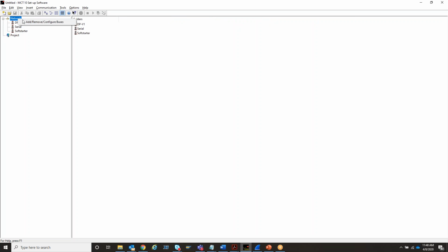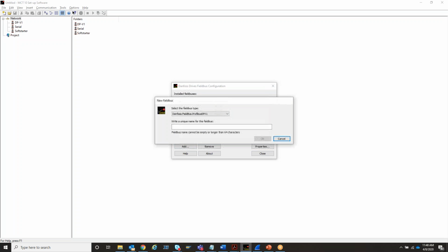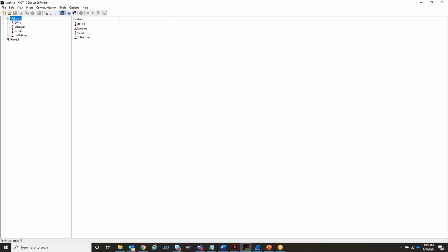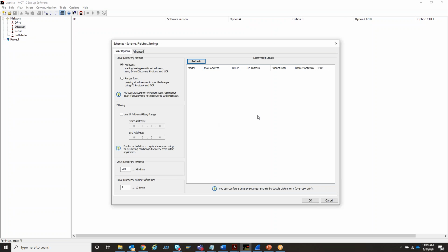So yeah, there's 2 different ways. I can connect through USB, or there's Profibus connection, but there's also the Ethernet. So I can actually connect to the drive over any of the Ethernet options through this Ethernet connection. And I can discover unaddressed drives through this.